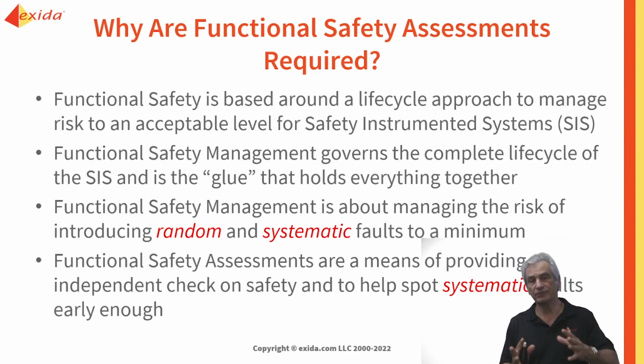We know that functional safety applies to our safety instrumented systems, and it's based around a life cycle. The purpose is that it's not just the planning and the designing of the safety instrumented system, it's of course the ongoing requirements to maintain it and keep up with the integrity requirements that we originally defined. Along with that, we have functional safety management that covers the entire life cycle. The way I like to characterize this is, if you think of it as the glue that holds everything together. So if we don't follow functional safety management properly, then we can pretty quickly become unstuck.